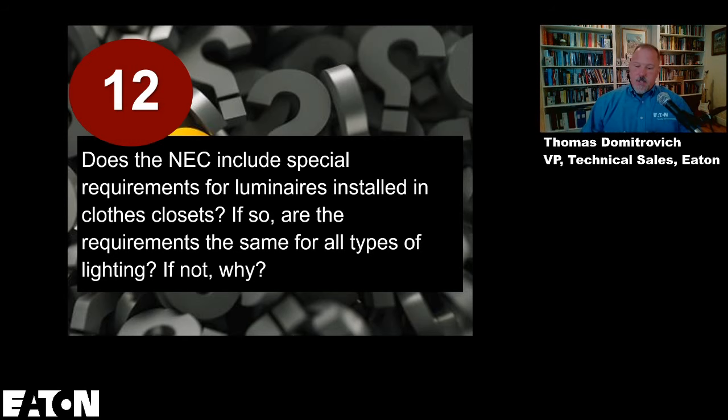So let's take a look at 210.6A. I don't know if you can hear my doggies barking up there. 210.6 is branch circuit voltage limitations. And occupancy in dwelling units and guest rooms or guest suites of hotels, the voltage shall not exceed 120 volts nominal between conductors to supply terminals of the following: luminaires, cord and plug connected loads.